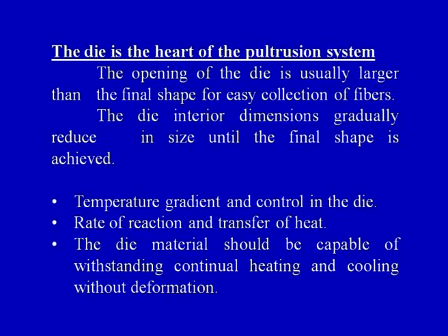The temperature gradient and control in the die is also equally important, because as soon as the raw material in the form of the resin impregnated fibers enter into the die, they encounter a certain temperature, and as they move forward in the heated die, the already heated fibers are moving in the die.